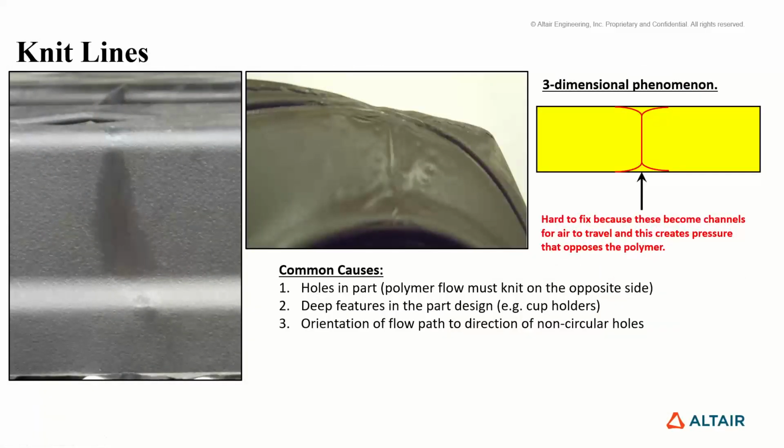Knit lines. Here's our knit lines, right? Here we have a nice shiny knit line. This is all texture, but yet here we have shiny. The texture isn't showing through here anymore. In fact, this can wear away your texture, having this kind of thing go on. And so what's happening is that the air traps and then the air blasts along the surface here.